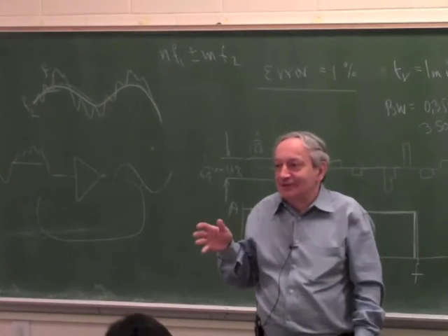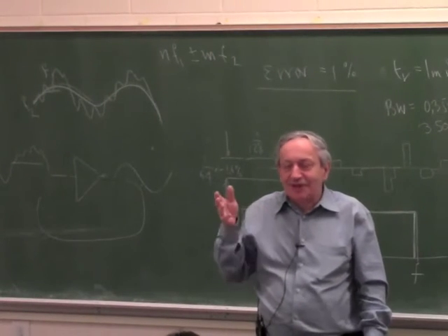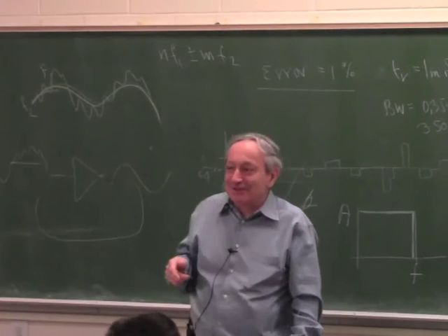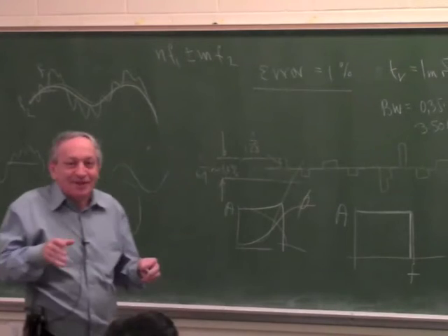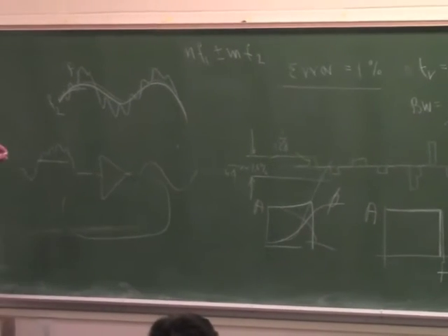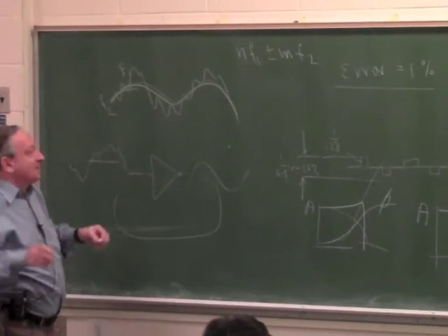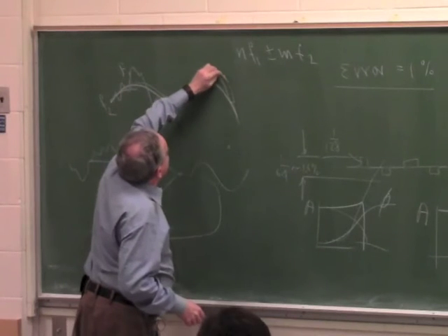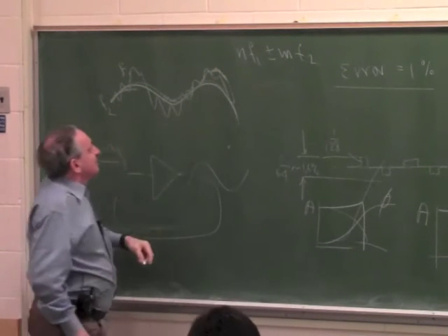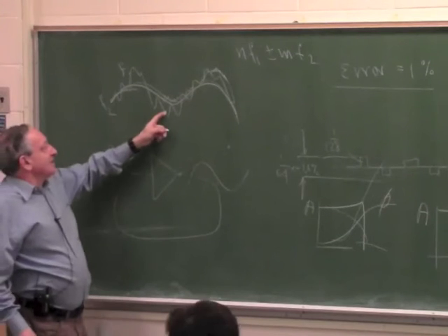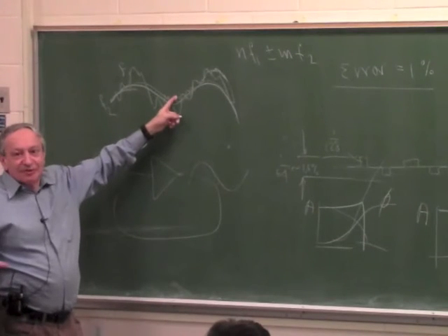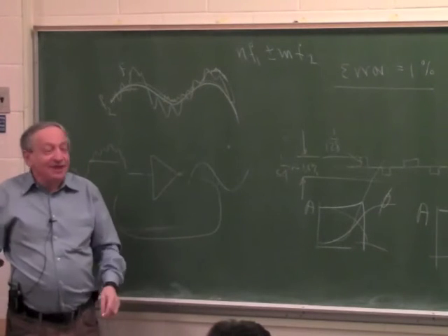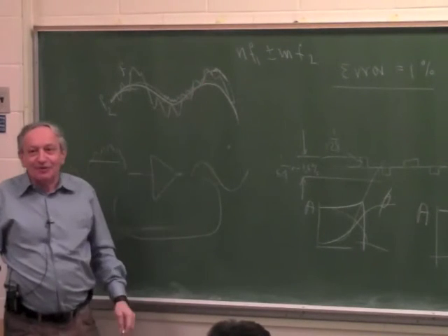And that's from? Where is the 1 gigahertz from? From you guys, smartphones. If you have a fast enough scope, you will see that on any low-level signal in the lab, there is this, and there is something faster, and there is something super fast, which you need a very good scope to see. And typically there is a 1 megahertz sitting on it, 100 megahertz, which is FM and television, and 1 gigahertz, which is smartphones. And today, probably there's a lot more of the 1 gigahertz than before.